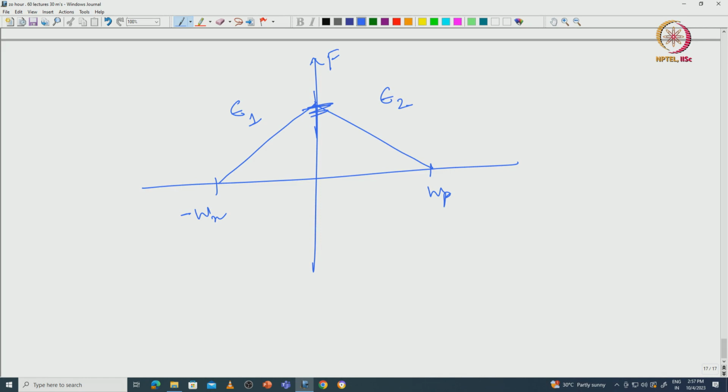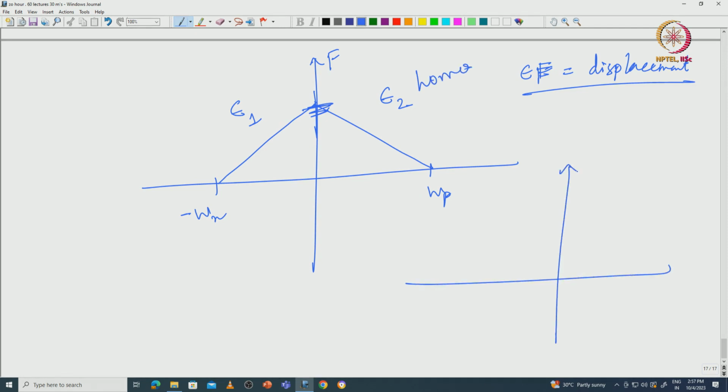Across this junction, what is continuous is the product of dielectric constant times field, it's called the displacement vector. So the displacement vector across the interface is constant, so the product of electric field and the dielectric constant is a constant. So what it means is that this was a homojunction. But if I come to a heterojunction, then depending on the dielectric constant, your diagram might look something like, say, this is one thing and the other might look like this.